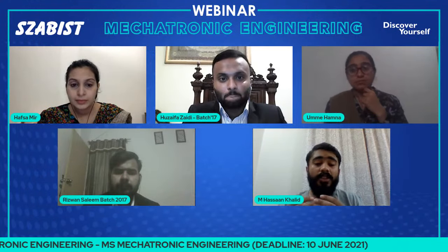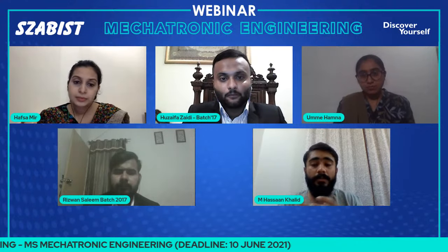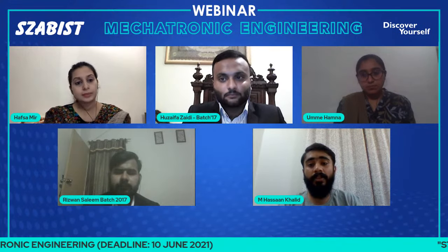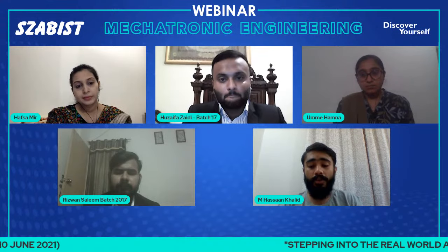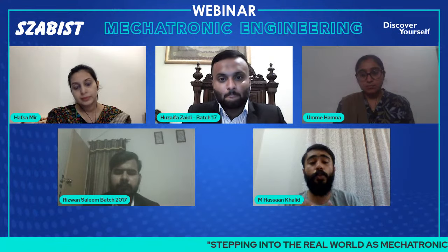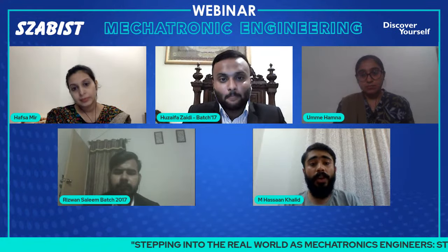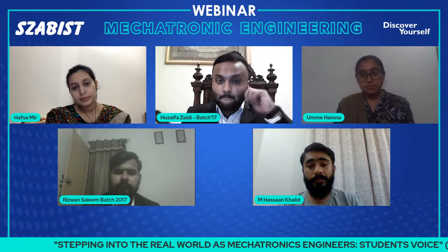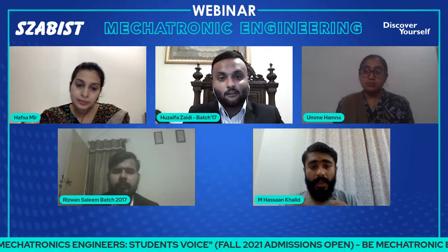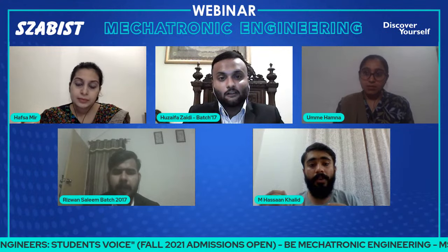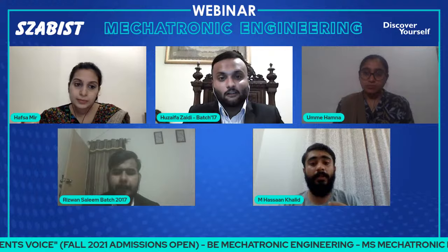And knowledge regarding power electronics, which is a course offered here at ZABIST in the Mechatronics department, was crucial for us because the power rating for our project was quite high. It was around 12 volts and 30 amperes. For that, we needed to make a protection circuit that could help us in safeguarding the power at the back end of the main supply.